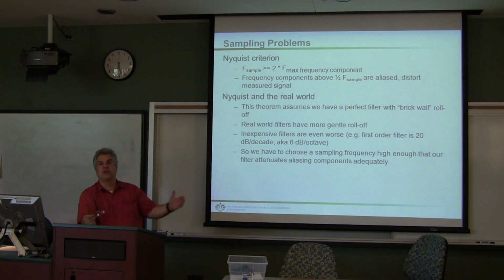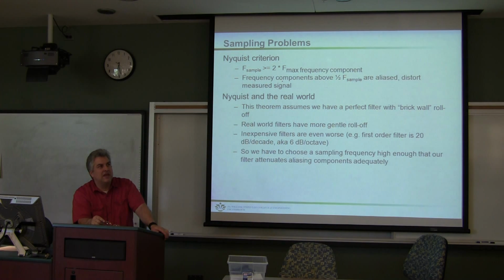So in the case of our temperature here, obviously you want to measure at twice the frequency of the change of our temperature. And our temperature changes about once a day, all right? So you can measure it once an hour, once every 30 minutes, it's good enough. However, if you're looking at something like an accelerometer, which is measuring the frequency of some vibration, and the vibration is at 2 kilohertz, you'll probably want to measure at more frequently than 4 kilohertz, right? Or more.